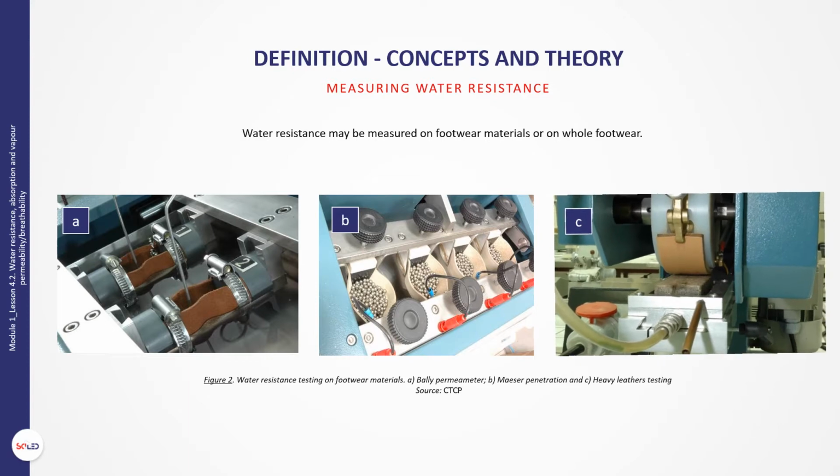The water resistance of heavy leather test method is applicable to soles made of leather. The test piece is continuously wet on one surface and is flexed and compressed in the same manner as the sole of a shoe during walking. This enables various aspects of heavy leather water resistance to be measured with respect to time. The standard testing method is described in ISO 5404, Leather Physical Test Methods, Determination of Water Resistance of Heavy Leathers.